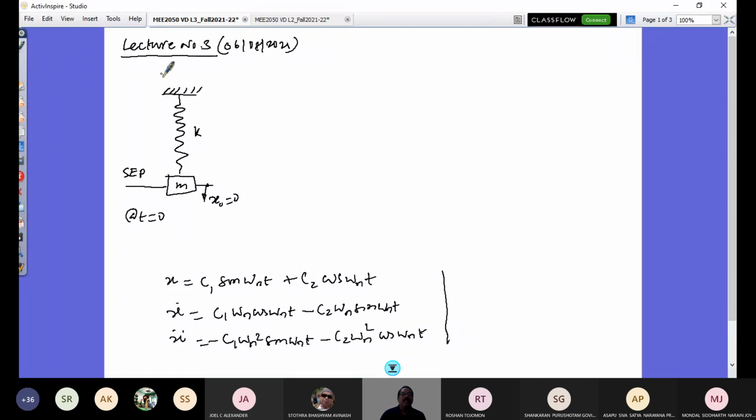So when you consider this, case 1, you can always make your simple harmonic motion start from its static equilibrium position. What is that? At t equal to 0, you have x equal to 0, and you will have an initial velocity, x dot, equal to Vm, the maximum velocity at its mean position, because once you give an impulsive force, it gains its maximum velocity, and then the velocity reduces till it reaches its maximum displacement. So at this position, it is this case.